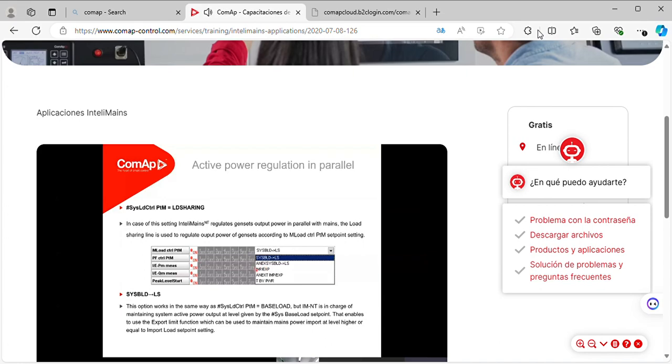So if you want to do grid paralleling and only supply back to the grid or only take a certain amount from the grid, you can set that. And the fourth option is external import and export. So you do not want to have a fixed value set through the controller, but you want it to be dynamically changed by an operator from the panel. So you can have external import and export.